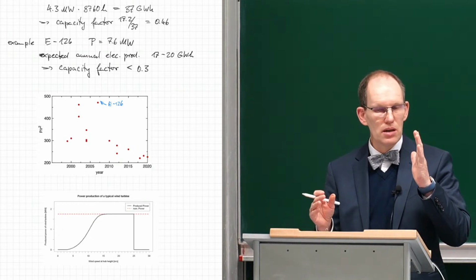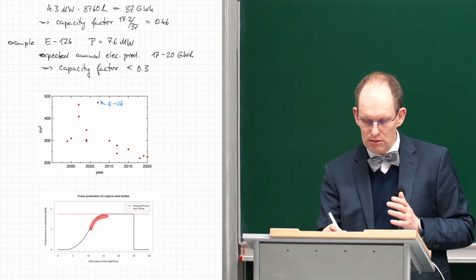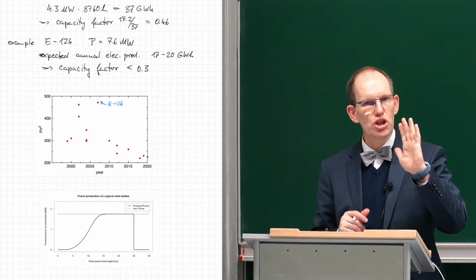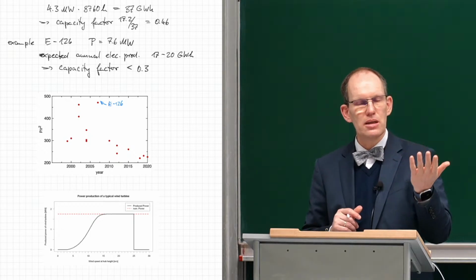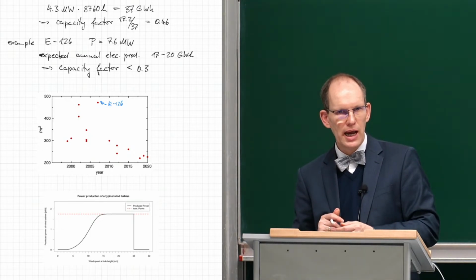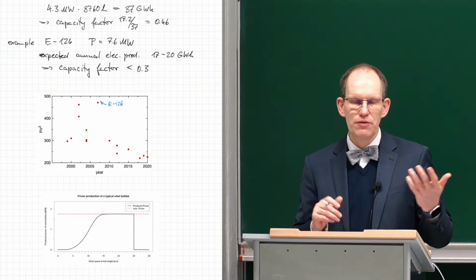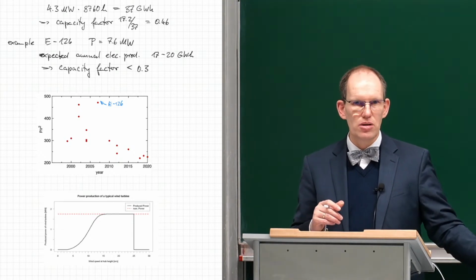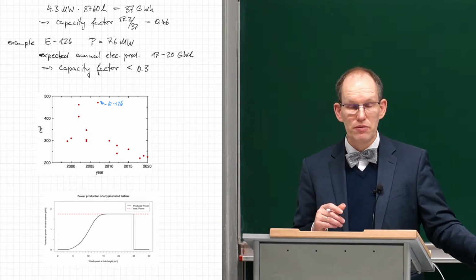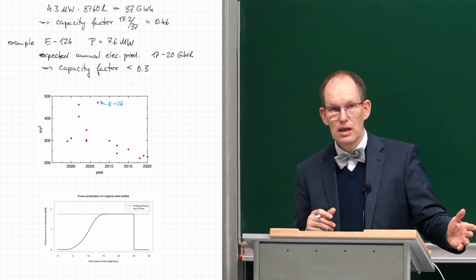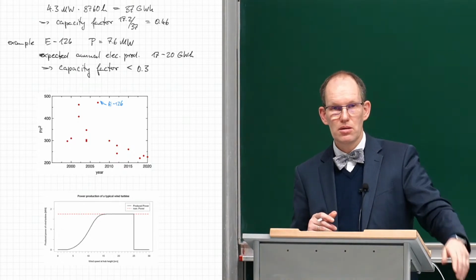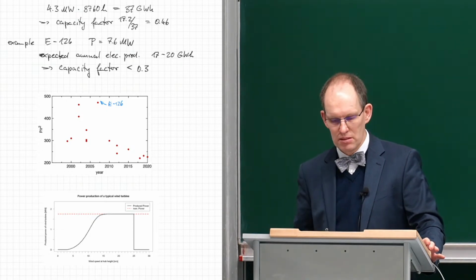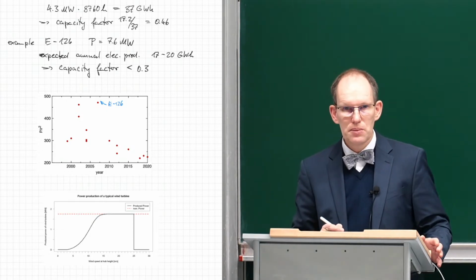So what you would do in order to get this saturation behavior would be that you pitch the blades such that they are no longer at the optimum angle. If you don't do that, then you destroy your generator, but probably before you destroy the generator, the windmill would be thrown over because the thrust on the windmill, as explained a few lectures ago, will get too high.